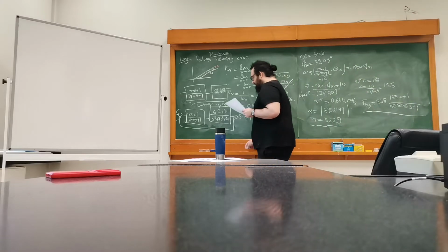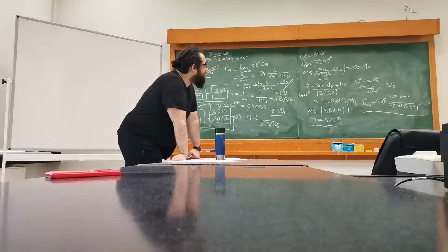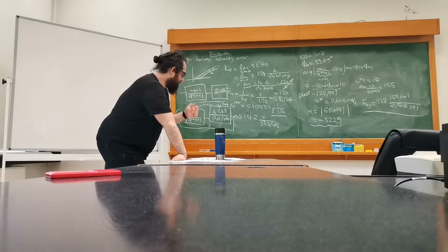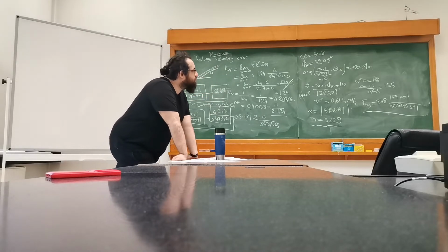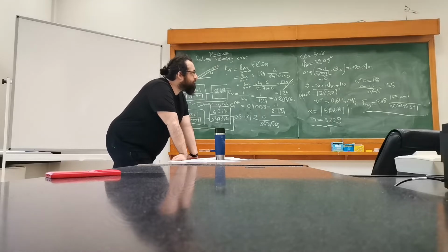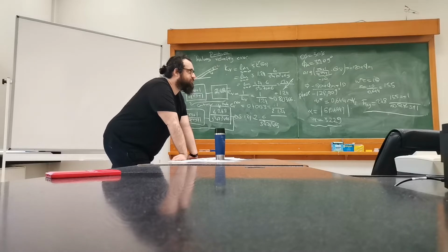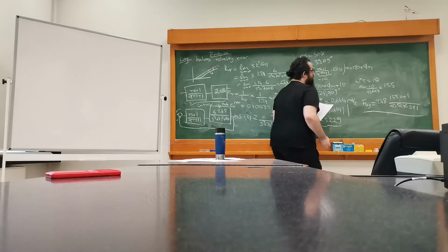So this is the frequency domain design. You can see that, again, it is pretty much algorithmic. You have a plan, you just look for the actual gain, the loop transfer function gain. If you have chosen that gain, then you just add it to the system or to the Bode graph. And once you have done that, you just look for phi m, but since you will have a contribution from a lag controller, you're just adding 10 degrees or assuming that it will be minus 10 degrees or less than that. So, yeah, what you can do is basically you can check out what the actual angle contribution is.